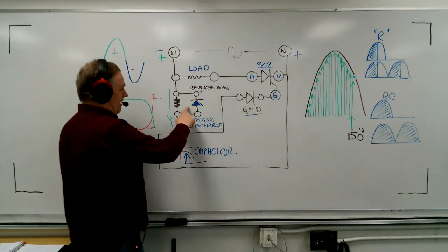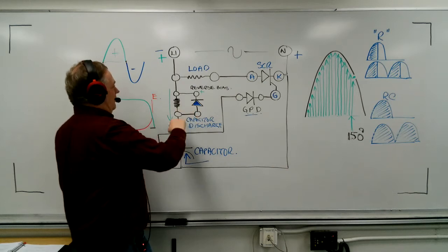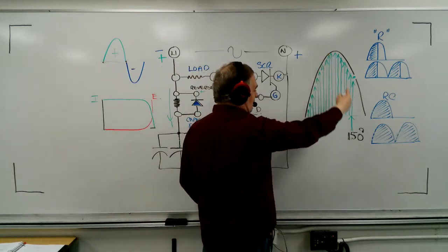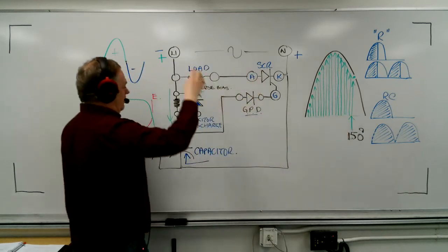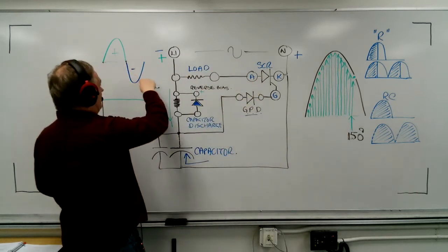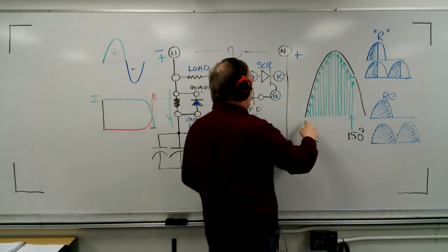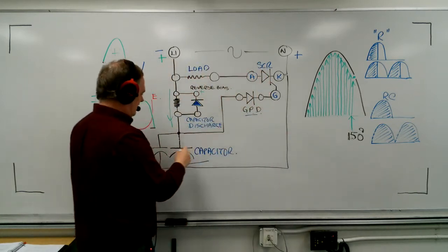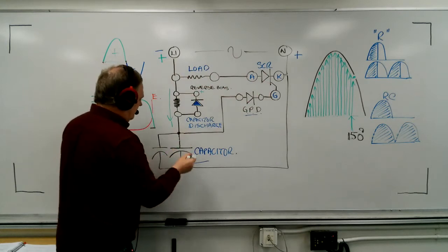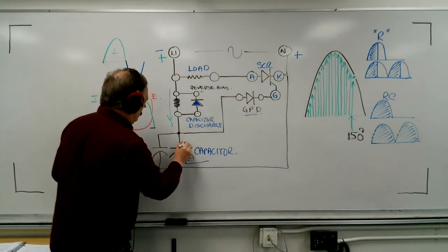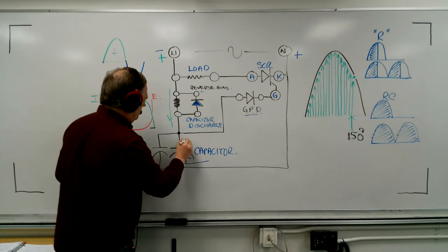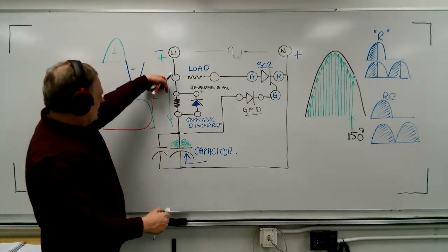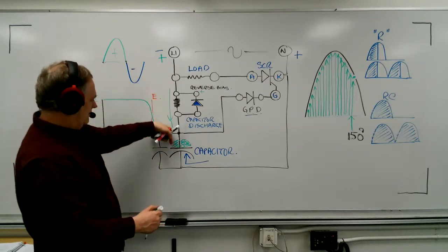If we didn't have this capacitor here, and this was my first alternation, where I got a firing angle over here, now went down, went through the negative, and I came back, and it's the second time now that I'm gonna try and get my firing angle. So imagine if there was already a bunch of charge here, okay? And I start trickling charge in through my resistor. It starts coming in.